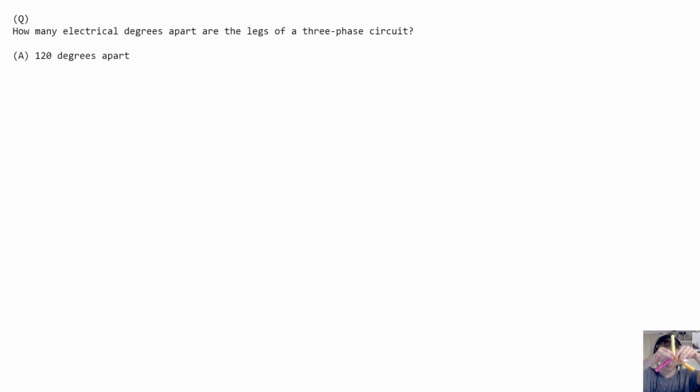Because if you have a spinning magnet going to three different, let's say, conductors here, and they're 120 electrical degrees apart, and they're placed here in this shape, we'd notice that if we're thinking about a circle, then since this is split up in three different sections, these are 120 degrees apart. Okay, so you have a magnet in the middle spinning, and when the tip of the magnet gets closest to any one of these conductors, that's the peak of its voltage.